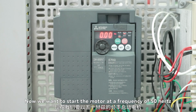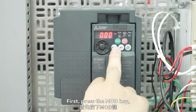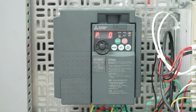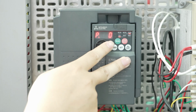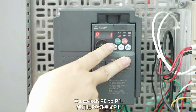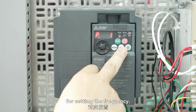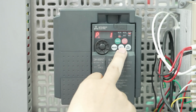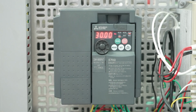Now we want to start the motor at a frequency of 50 Hz and see how to set the frequency. First, press the mode key, and you can see that the mode has been switched. We switch P0 to P1. P1 is the corresponding position for setting the frequency. Then after we switch to P1, press the set key, and it will enter the frequency setting.